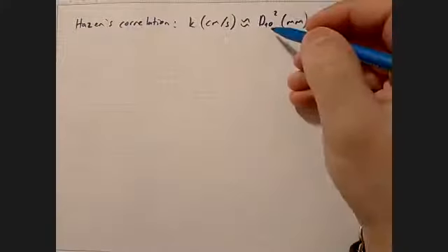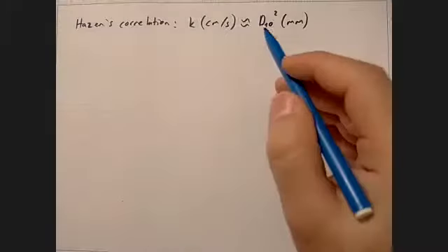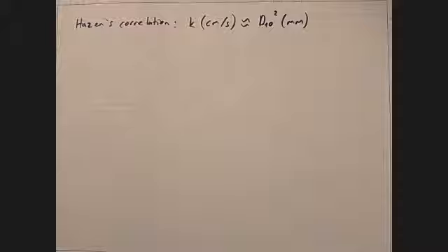Why is this d10 but not some other diameter? It is because the pore size is controlled more by the smaller grains, because the smaller grains are able to fill the gaps between the larger grains as well. So your pore size is generally related to the small grains.